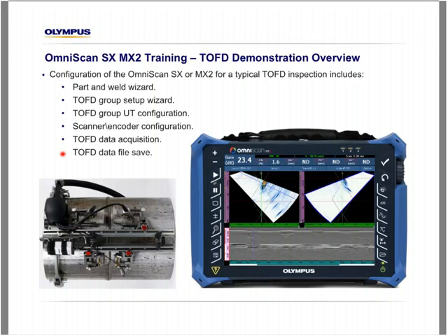In this example, we see a very typical 2-phased array probe and single TOFD inspection. That would be a 3-group inspection of which the TOFD uses a single A scan.